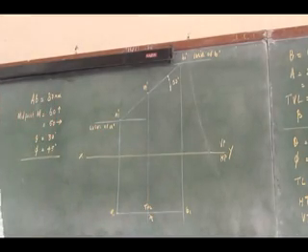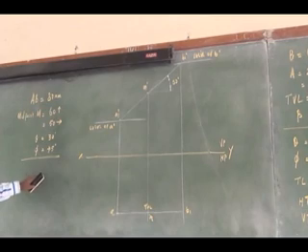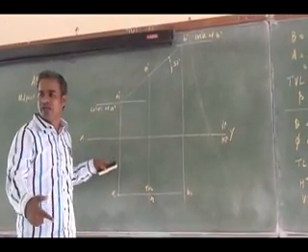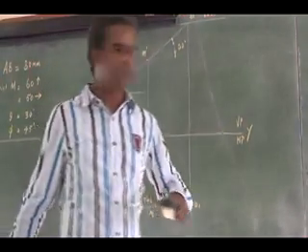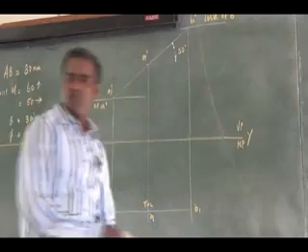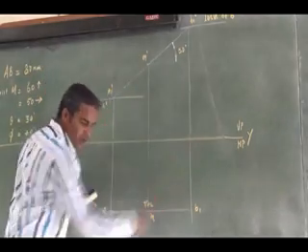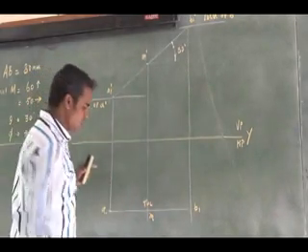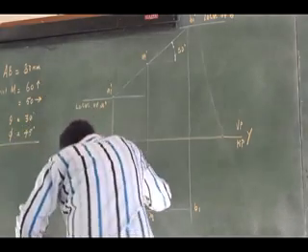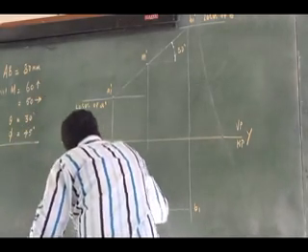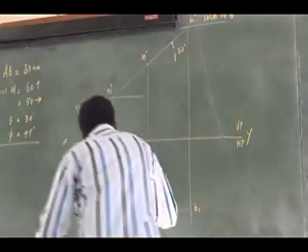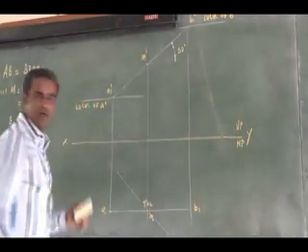So similarly, using the second assumption, I can use the true length and the true inclination 45. Okay, this 45. From where I have to measure? From M dash, I have to use the true length and the true inclination 45. So how I can measure it? Either this way I have to draw it or this way. So similar to the previous problems, you use the same orientation. So 45 I have to measure it from 45 degree angle. I have to measure the true length here.